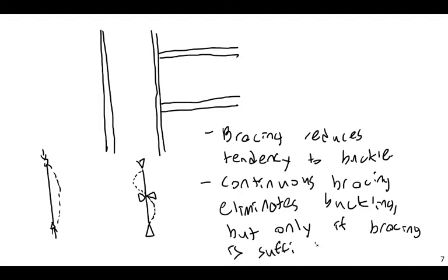No brace is infinitely strong, especially a brace that is nothing more than another element of the steel section, unless it is sufficiently strong. So no brace is infinitely strong. Again, in this example, if I have a steel column and I bring in an enormous steel beam and connect it up properly, yes, that's going to act as a big, strong, proper brace. The column is not going to buckle at that location. However, if I connect it with something disproportionately strong, or not of compatible strength.